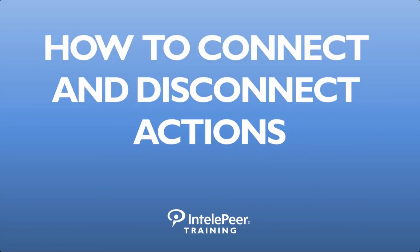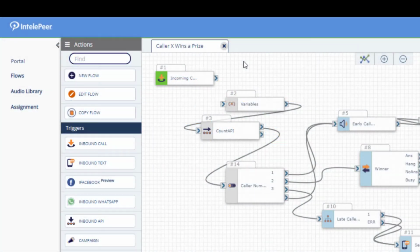How to connect and disconnect actions. Actions are connected in a flow in the order in which they occur. To connect one action to another, select a port on the action and hold the button on your pointing device. A connector appears and follows your pointer. Drag to the port on the other action. When the port lights up, release the button.